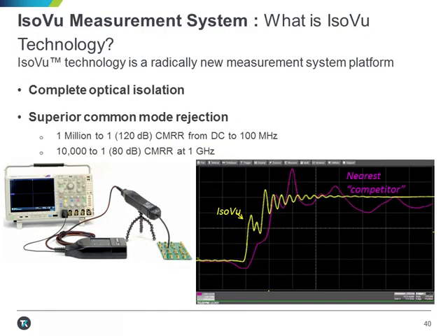The second thing that is new at Tektronix is a new product introduction, the IsoVu Measurement System. What is that? Simply, whether you're designing an inverter, optimizing a power supply, testing communication links, measuring across a current shunt resistor, or debugging EMI and ESD issues, common mode interference has caused engineers to design, debug, and evaluate, as well as optimize, in a blind way. Revolutionary IsoVu technology uses optical communication and power over fiber to achieve complete galvanic isolation.